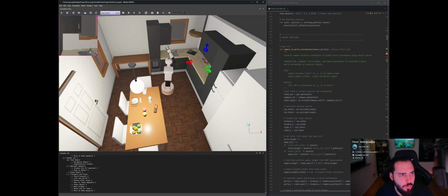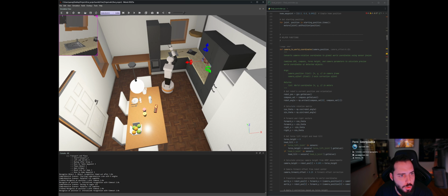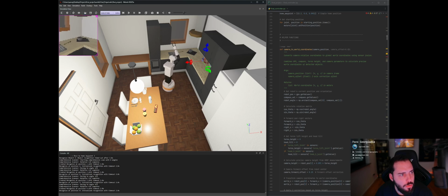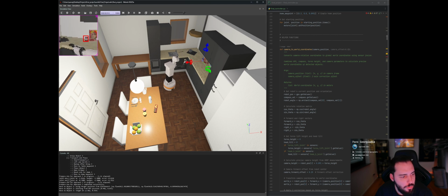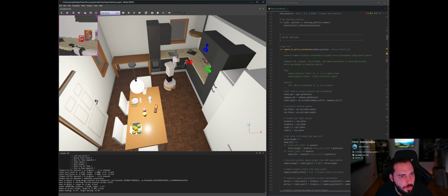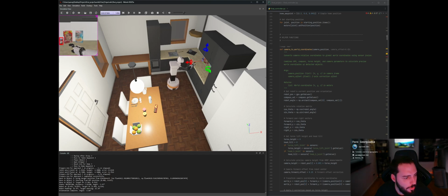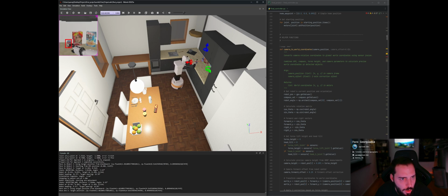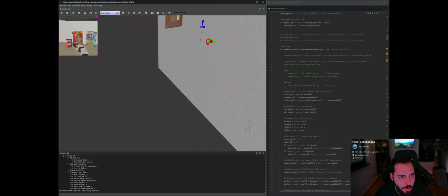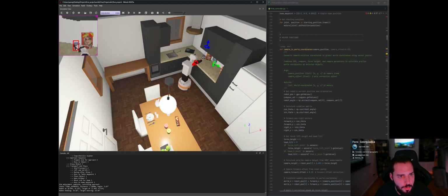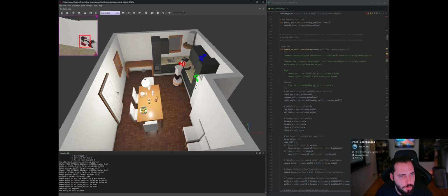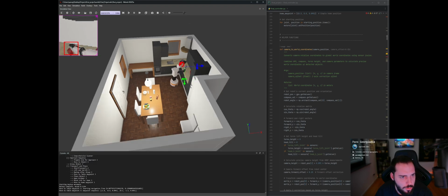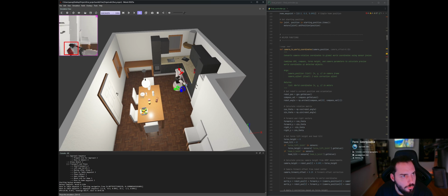Now we have the final and third jar. Same thing, doesn't recognize an object right away after 3 seconds. It then moves on to the comprehensive scanner. And then you'll see right as it goes into view, there you go, recognizes the object, figures out its location, puts its arm in a position to get ready to calculate the inverse kinematics, moves to the target position at 1.28 meters away, calculates the position it needs to be in, grabs the jar perfectly, it verifies that it's grasped it, backs up, lifts and verifies that it still has it, and then goes to the table.